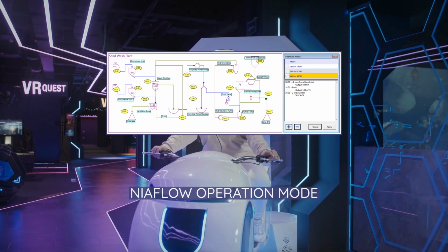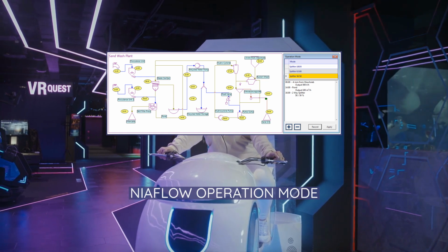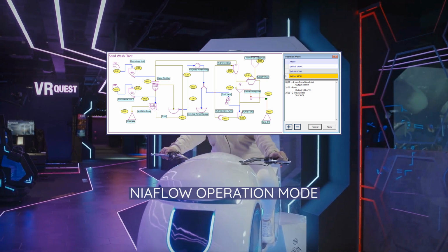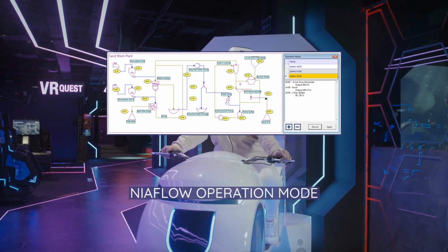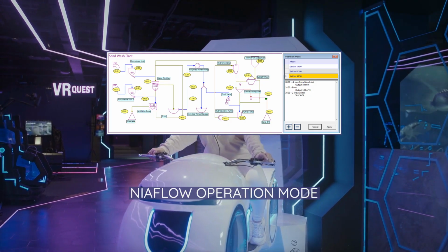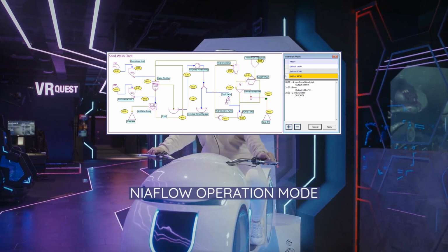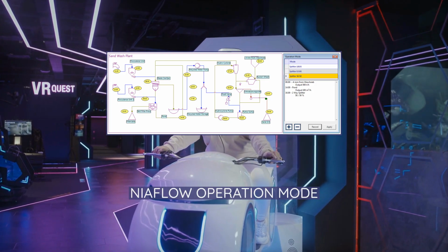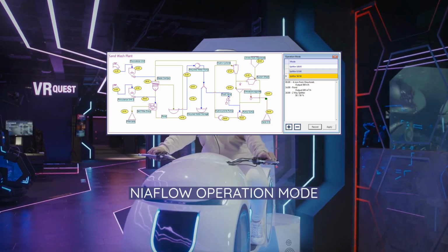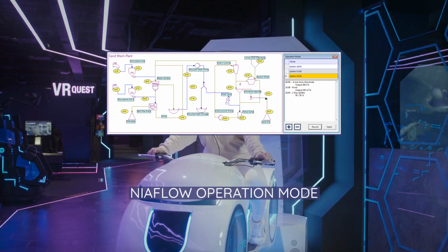Classifying objects are various screens as well as objects that can be set up for either sorting or classifying, e.g. upstream sorter/classifier. Classifying is performed by means of cut curves, Trompe curve. Trompe curves describe the probability for a certain material fraction to arrive in the coarse product. For screens, NIAflow generates cut curves automatically based on the machine and media setup. For other machines, user input is required to define the cut curve.